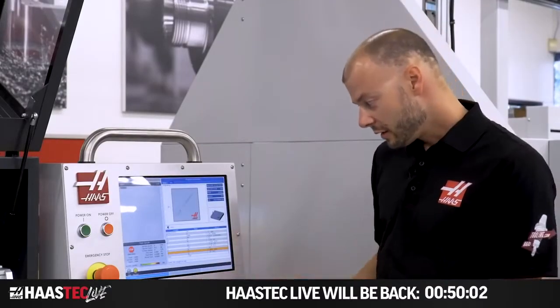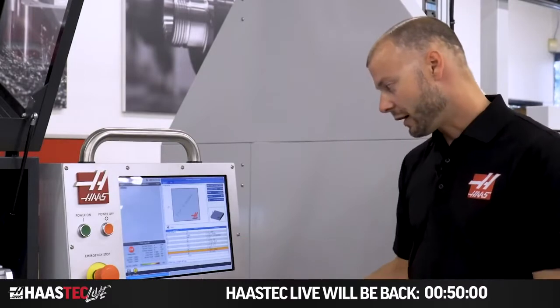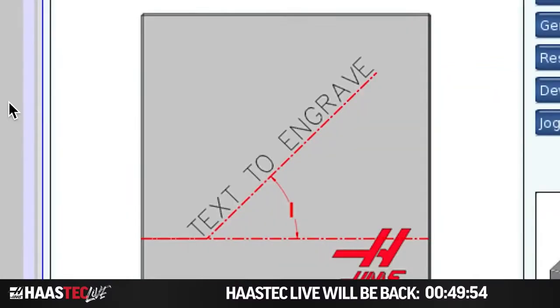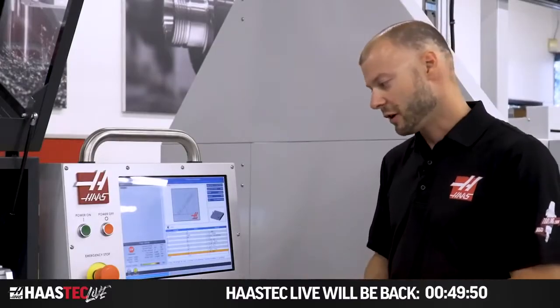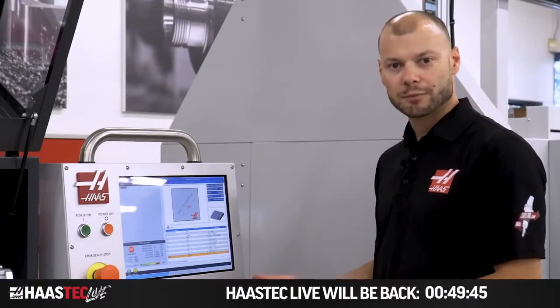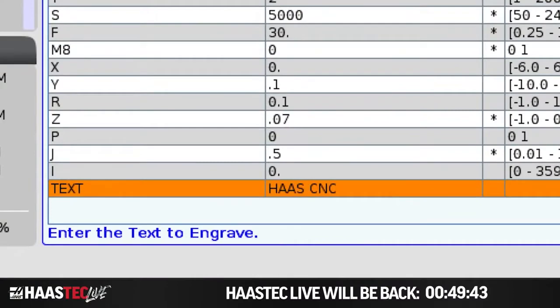And it's asking how high do I want it. A half inch looks good to me. And do I want it on an angle? In this case, no, I'm going to go straight across, but you could also do it at any angle around the circle. And now at the bottom, what do we want to engrave? How about Haas Technology CNC? And that's the last line of this template.